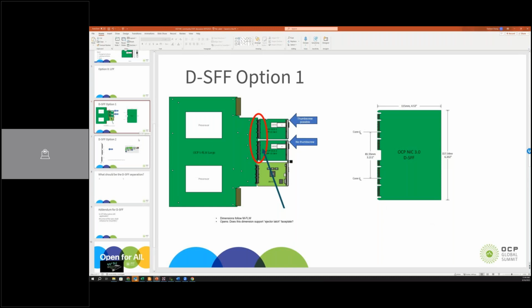For example, if I look at the olive green connector on the top, right, where does it go? To a drive? On the two, very top is power supply. These two bottom are the CRPS power supply. So I can imagine that if you push the upper PCI SFF up, then you don't have room for that? Or is there enough clearance there? That's what I'm trying to understand. Yeah, I think where he's going is if they were to move to the wider spacing, you could support a thumb screw on the middle Type 3 when you put two single Type 3s in.